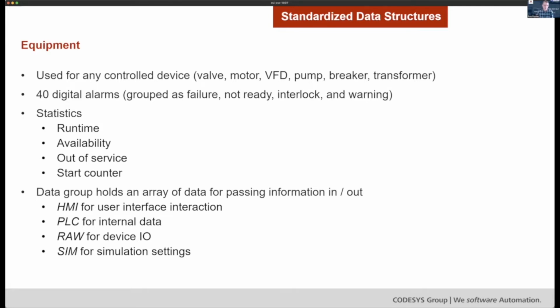So for instance, for any failure alarm active, I can have 1 bit that turns on if one of my 10 failure alarms is on. And then of course I can use that for shutdown purposes or things like that. And, you know, we arbitrarily kind of set these because this works for this industry, but they could really be grouped however, and used however.